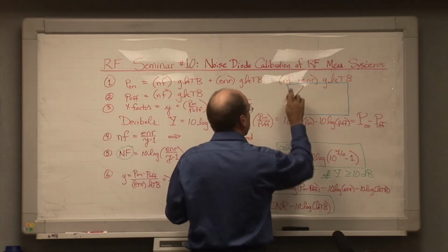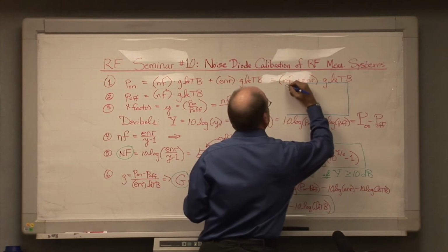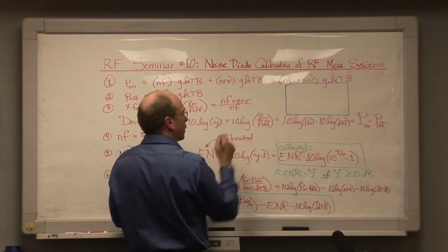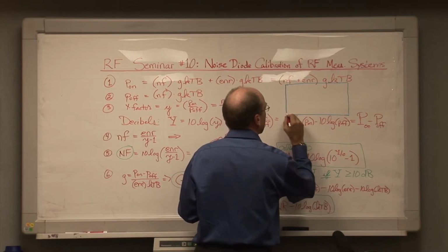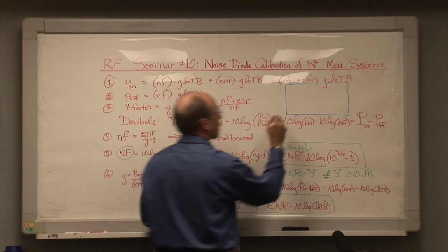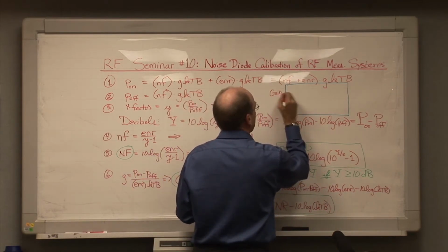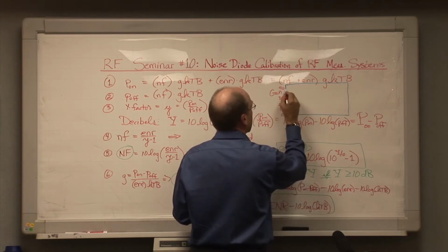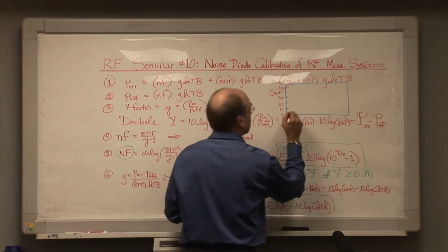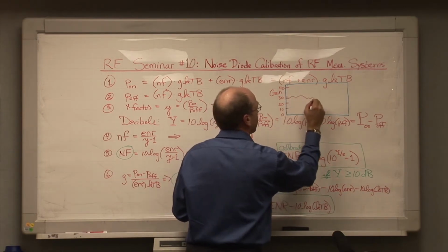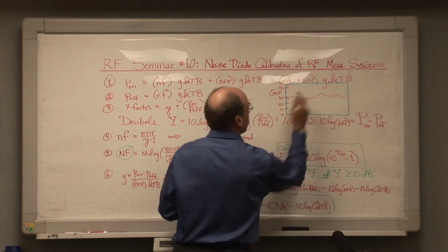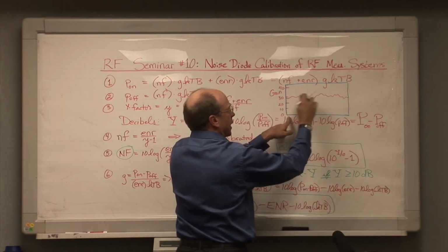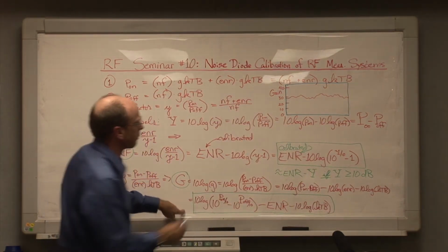One curve we can graph will be the gain. Actually, I'm going to draw this the way the software does it that we're going to see in a second. So this axis will be gain, and this will be say 40, 30, 20, 10, and 0 dB gain, like so. So we might measure and calculate gain across some frequency range like this. I should note that this is frequency range across here. We get gain as a function of frequency because we do this calculation for gain at a set of frequencies across the range, graph it like that.